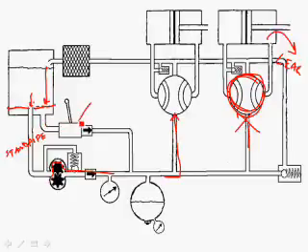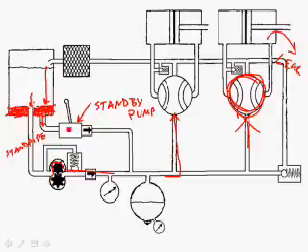But you'll notice that this standby pump here is pulling fluid in from the absolute very bottom of the reservoir. So the reason that the standpipe is higher than the bottom is that if you have a big leak and you can isolate it, the standby pump will still have some fluid to operate the other components.